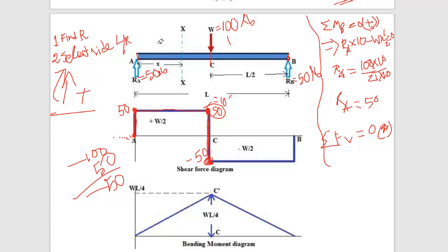Understand, sir. Okay. So until you reach the point B, there is no disturbance. So till you reach point B, you can continue. And after that, you can see this 50 is acting upward. So you have minus 50 and upward force is positive. Minus 50 and plus 50 equals 0. So keep in mind, for determinate structures, you should end at the neutral axis.